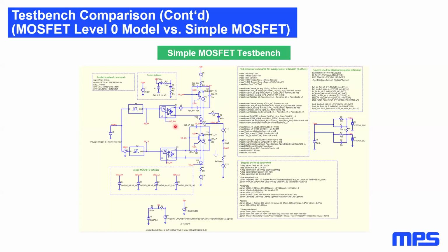One can notice also the presence of the operating region and the junction temperature nodes for each MOSFET. Ultimately, a thermal behavior of the package has been included to determine the FET's junction temperature increase due to the power dissipation estimations which are made at simulation runtime. The measurement statements' complexity also is visibly increased in order to allow for the calculation of the different contributions to the power dissipation.